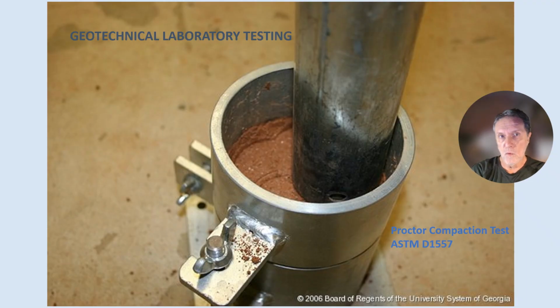Basically, what you want to test them for is their material properties like strength, moisture, density, and you also want to find out what their texture is, whether they're clays, silts, or sands, so that you can classify the soils. All these properties are crucial in determining foundation types, the type of mitigation or soil improvements you may have to undertake. So the laboratory is the next step after the field, in between field investigation and report writing.